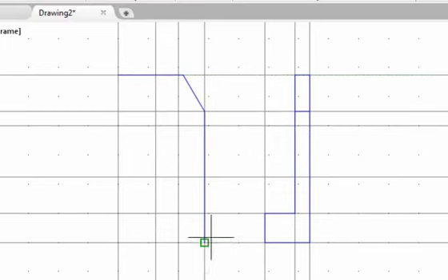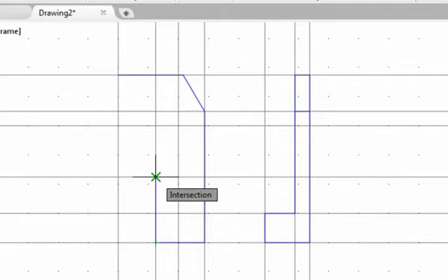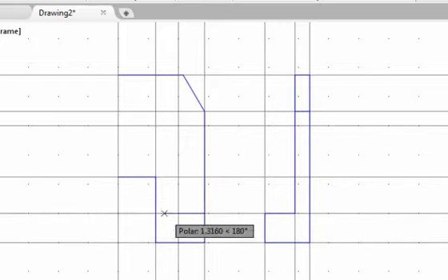We will now create more line segments starting at the bottom right corner of the front view. Go to the second intersection point towards the left. Go to the intersection directly above the last point and create one more horizontal line towards the left. Hit the spacebar again to repeat the line command. We will now create one more object line in the front view. Go to the second intersection point from the bottom. Create the horizontal line representing the base of the design.